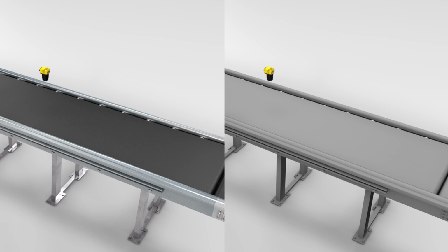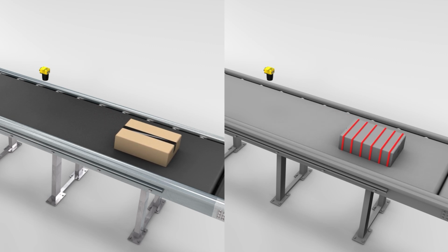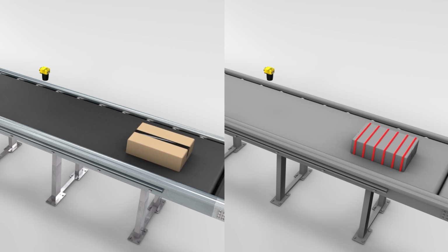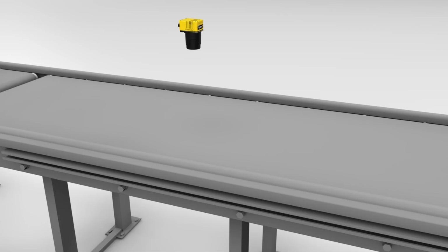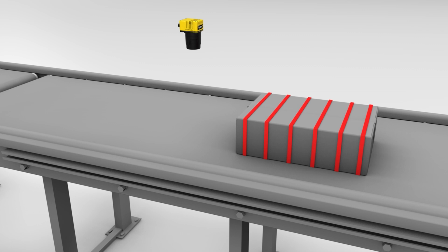Line scan devices, like the In-Sight 3800 line scan, require an encoder to build an image. They acquire a line or cross-section of an object right below the sensor. Therefore, the line scan camera or the object must move to capture multiple lines that will be stitched together to form the image. The encoder keeps track of the spacing between the lines by tracking the motion of the object being imaged.